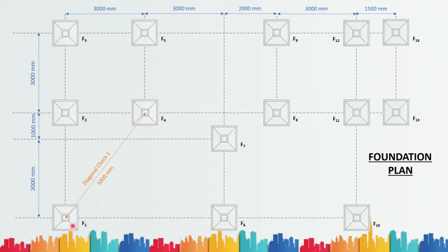So what will happen at site is, once you have marked this and this distance, you can quickly put the chain across, I mean the tape across this, and see whether this comes at 5000. If this comes at 5000, that means the positions of these three columns are correct. Similarly, we can take a bigger example.